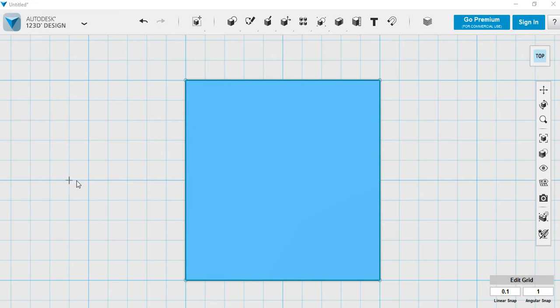So I'm going to draw a circle, 10 in radius, and you can see that the measurement it gives me is the diameter. So the diameter of the circle I'm going to draw there is 20 millimeters. And then click. On your drawings, you might not be able to tell by looking at the front view what shape your object is, but that's up to you. If you want your object to be circular, that's fine.